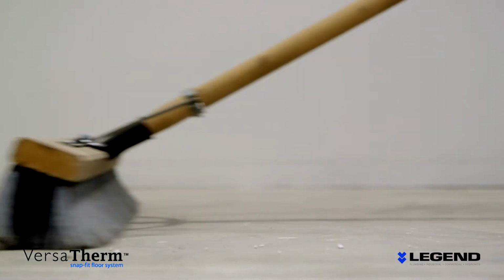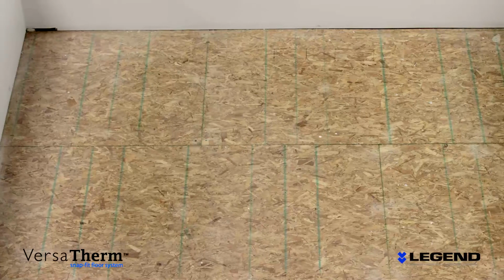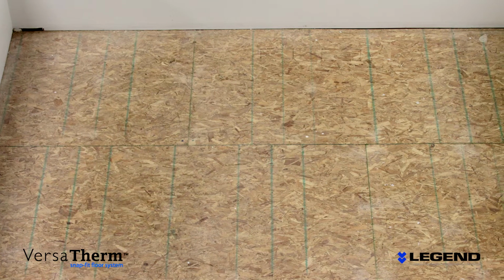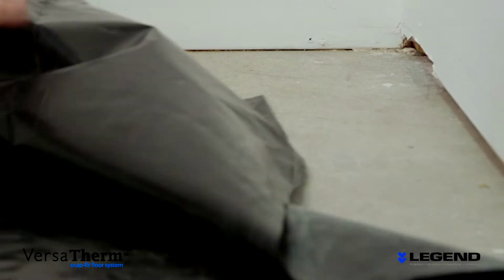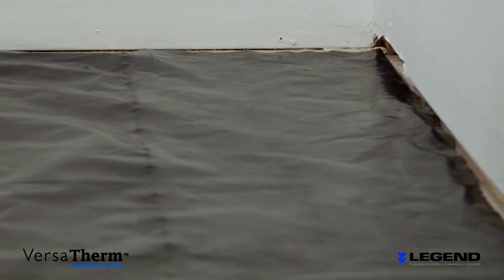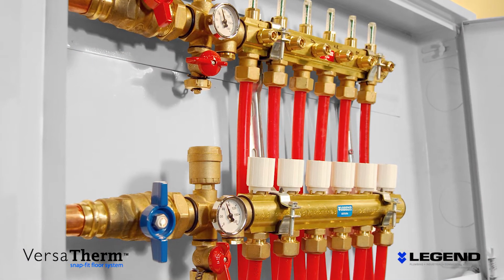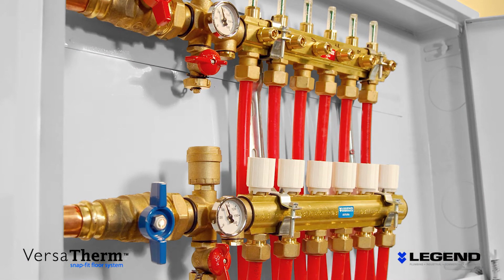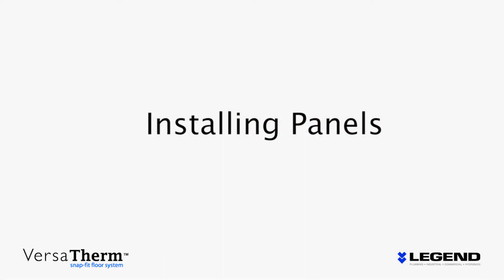The subfloor or concrete slab should be clean and as level as possible. Also, the floor must be structurally sound. Do not install VersaTherm on damaged or rotted floors. If using VersaTherm on a concrete slab, a vapor barrier between the slab and the VersaTherm panels will be necessary. The manifold supplying water to this section of floor should already be installed with the fittings available to attach your tubing to the manifold. With the site prep completed, we're ready to lay down the VersaTherm panels.